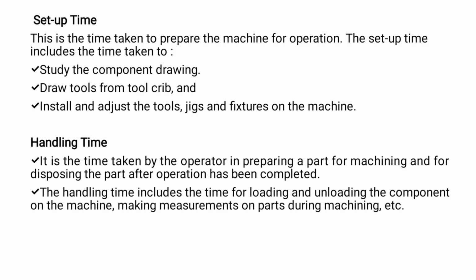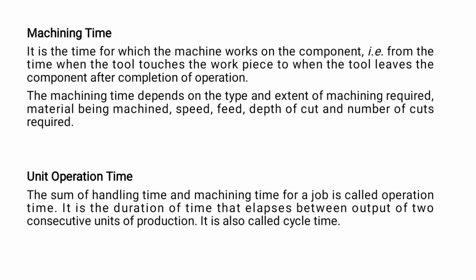The handling time includes the time for loading and unloading the component on the machine, and making measurements on the parts during the machining. Third one is machining time. It is the time for which the machine works on the component, that is from the time the tool touches the workpiece to when the tool leaves the component after completion of the operation. The machining time depends on the type and extent of machining required, the material being machined, speed, feed, depth of cut and number of cuts required.